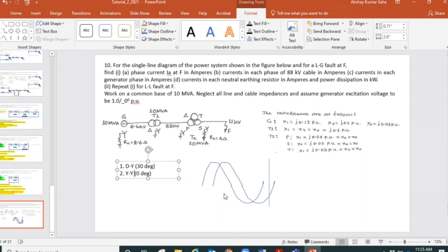Then he told me that there were some transformers that were operating fine, no problem, but all of a sudden the transformer had some problem and tripped, and then we had to isolate the transformer and find out the faults. And as you have now disconnected it, you have to reconnect it. And when you're reconnecting it, you need to again make sure that you maintain all those conditions, starting from the phase sequence, R-Y-B connected to R-Y-B, and the frequency. No problem, we know it's going to be the same frequency, 50 Hz, but again, the vector grouping is the major one. So when I taught him, he told me that if he could not do that, he would have lost his job.